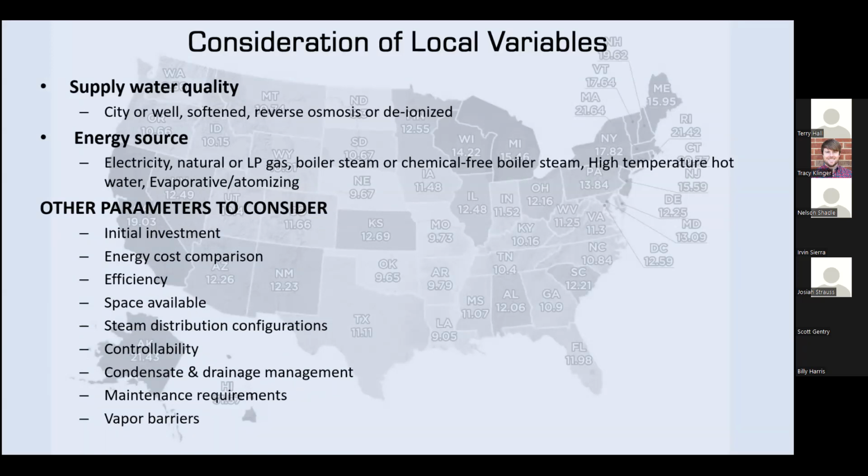It depends on whether you get your water from the mountains or from groundwater. Generally, if it's from groundwater, it's going to be a little more challenging because that water is sitting in an aquifer and absorbing minerals, and when you boil that water, it's going to precipitate all those minerals in the tank, and that creates a service requirement or a requirement for water treatment.